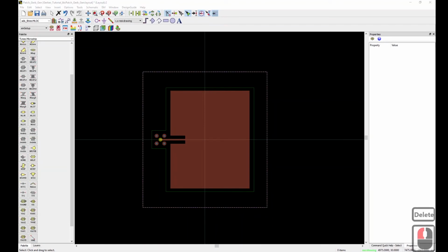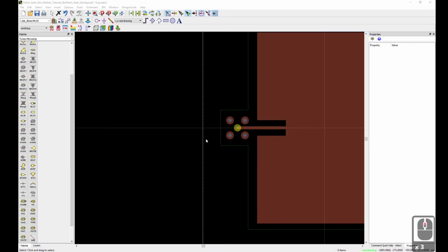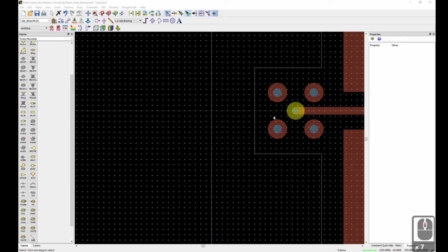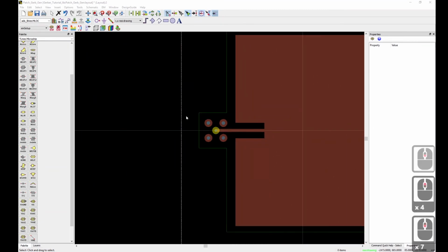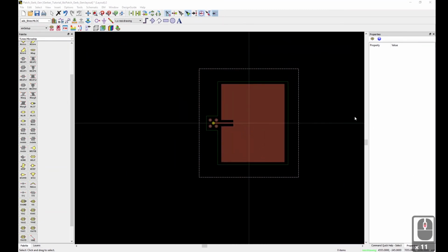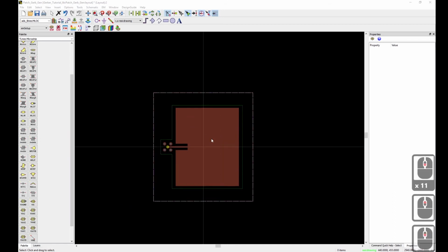Okay, so the final step here is going to be to add some what are called fiducial holes. So you see here that we've basically got a two-layer design, even though it's very simple. We need to do some rubbing out on the back, and then we have to do milling on the top, which means that the milling machine has to do some alignment. And this can be done by adding what are called fiducial holes to your design. The milling machine can find those holes and reorient the coordinate system when it's milling in order to align the two sides of the board.